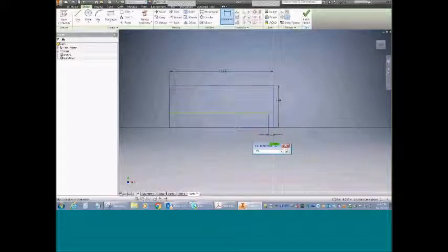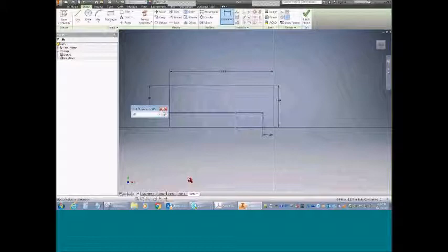That should be 1/4 of an inch, and then this should be 1/4 of an inch as well. So as part of the design intent, I would make sure that they are interrelating dimensions and that they're starting to set up equations in their dimensions, so that you communicate the design intent. You change one thing, and everything else that needs to change does change on its own.